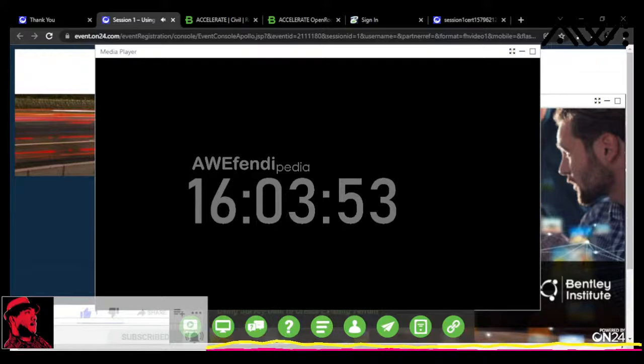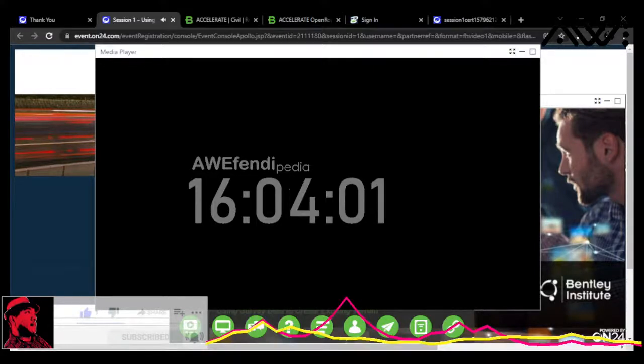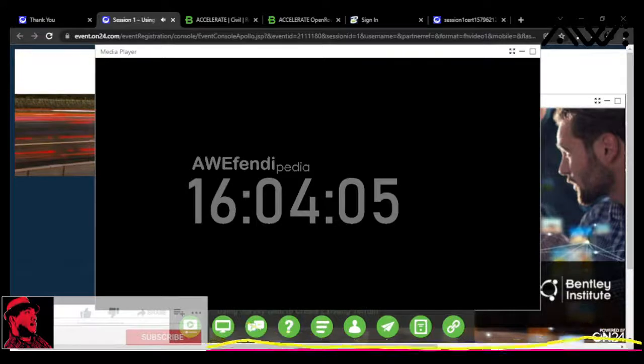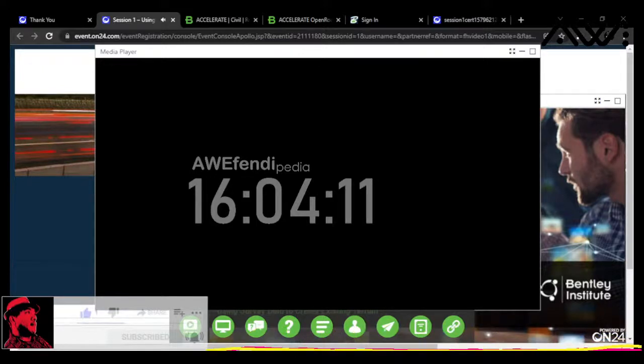I'm going to hit open, and the program is going to present to me all the different text file options. And those were set up in the settings back in the OpenRoads standards there. So I have these different options for text files. Mine is this very top option. It's a comma delimited. It's a point name, northing, easting, elevation, and code. That's the order that the information was in there. So I'm going to pick the top option there.